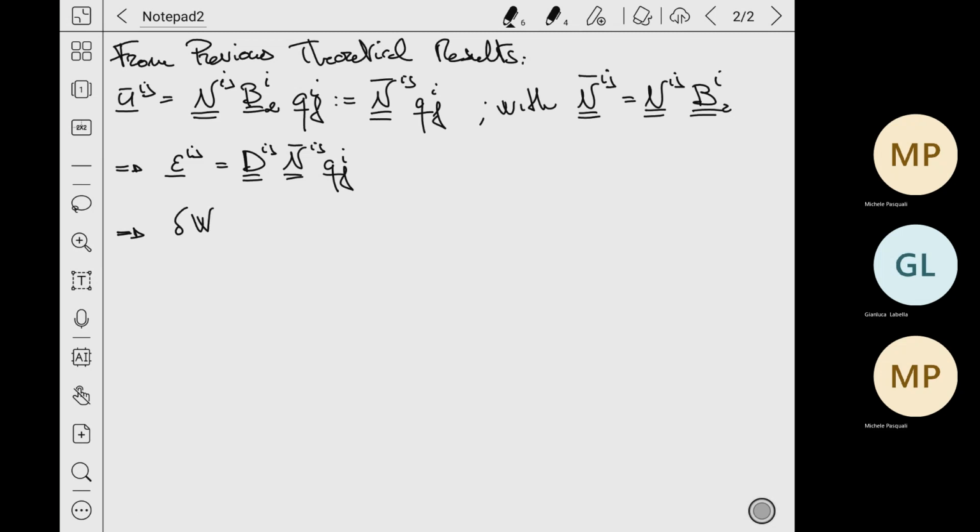virtual work of the elastic forces can be written as minus qfI transposed applied over Kffij applied over qfI, where this Kffij, which is the structural matrix of the element, is, as you can easily imagine, something very close to what we have already seen.